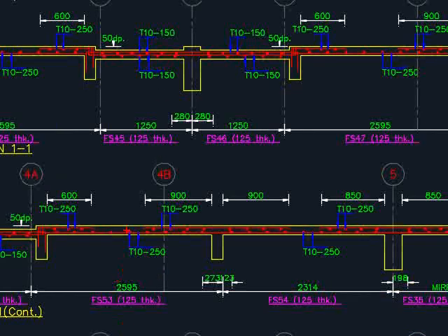Sometimes you may have the main reinforcement bar and the secondary reinforcement bar similar to the adjacent members. You can actually have the reinforcement bar to be continuous without providing the required lapping length. This can increase the productivity of the construction work on site, where the workers do not need to cut the reinforcement bar and do the lapping.